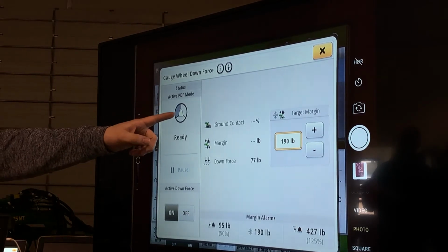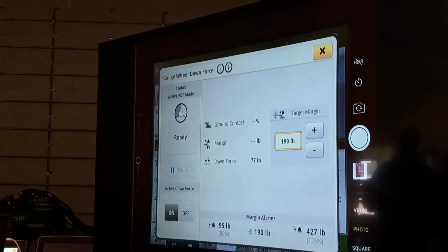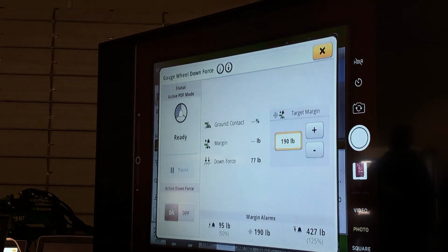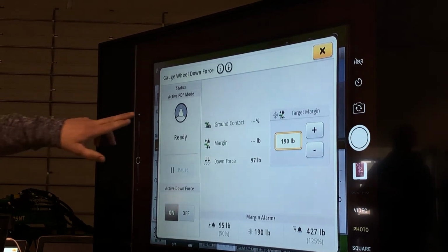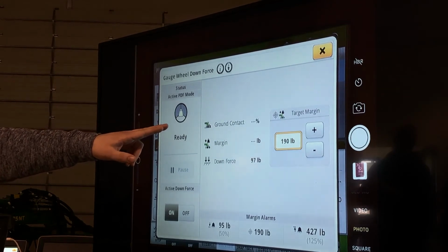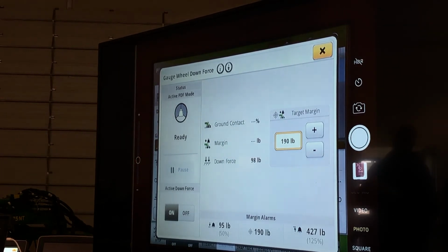This top right third, that's our speed portion. We actually need two speed sources. One, we need a tractor speed, whether that's coming from the radar or GPS. And the other one we need is the planter motion wheel sensor, which, John, we have a radar simulator on both of these. That wheel motion sensor on the main frame is usually found on the furthest left wheel, from the back of the planter. Once we have both of those, we can see that did fill in a solid gray, so we know that condition is met.